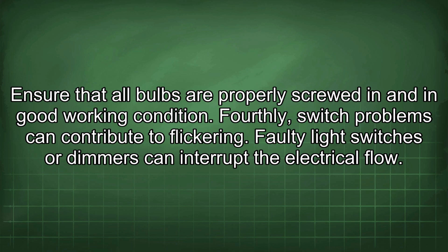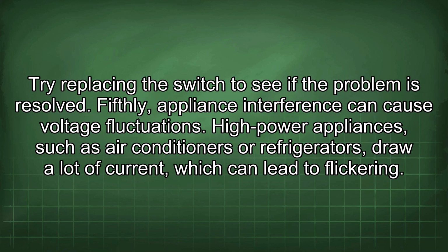Fourthly, switch problems can contribute to flickering. Faulty light switches or dimmers can interrupt the electrical flow. Try replacing the switch to see if the problem is resolved.